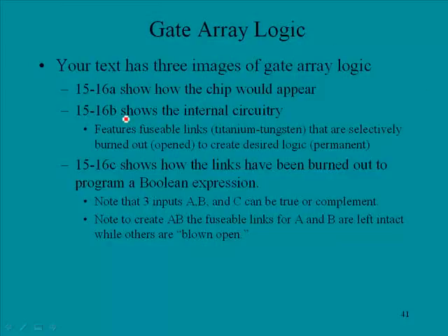Then 1516B shows the internal circuitry, and it features fusible links, and these are titanium tungsten that are selectively burned out to create the desired logic. When they are burned out, these become permanent, so there is no changing. Now, there are some that are actually programmable, though this particular one is permanent. So you have to make sure you've got the logic right, because if you don't, you'll have to throw the thing away and start over.